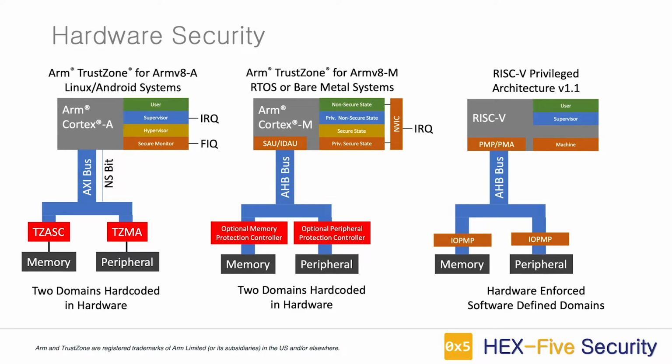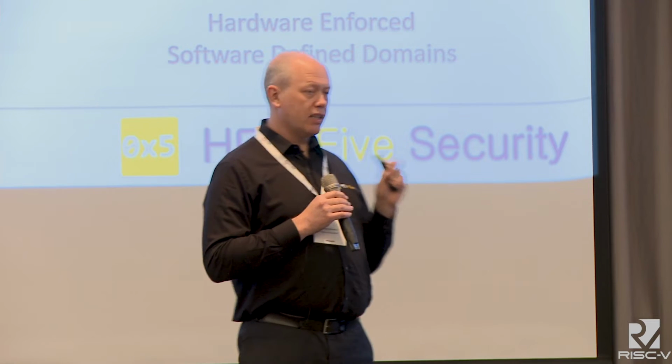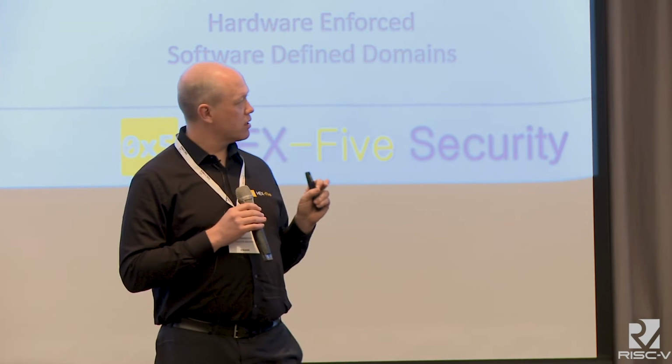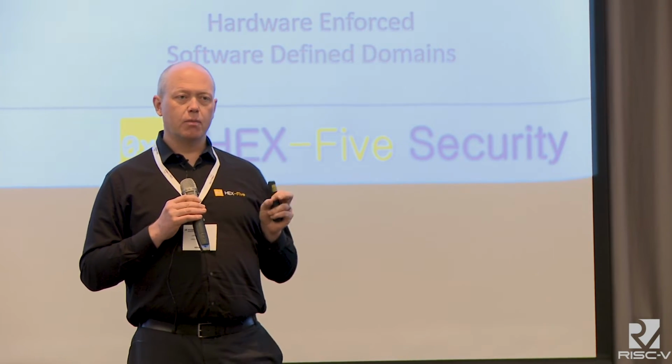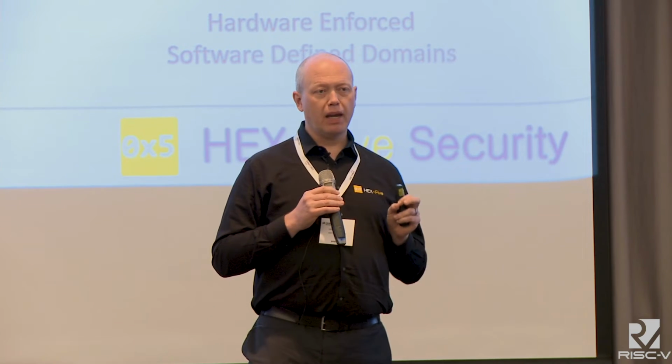Downstream of that, for other bus masters, we have an IO-PMP concept, which some of you may have heard of and some of you may not have, but it's a way of recreating that PMP structure on other bus masters so that you can also filter those and ensure that your DMA controller can't write all over all of your other protected structure. To us, this one's really interesting because this one's hardware enforced, but now we're not really locked anymore. Now we're into the software-defined domain world.